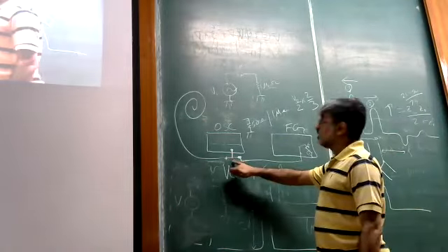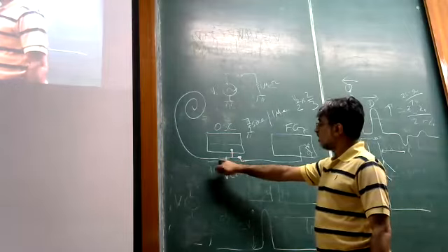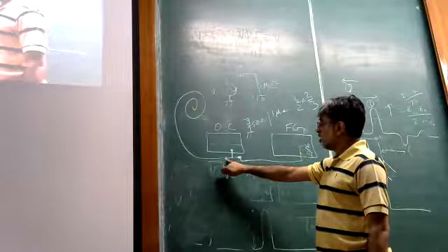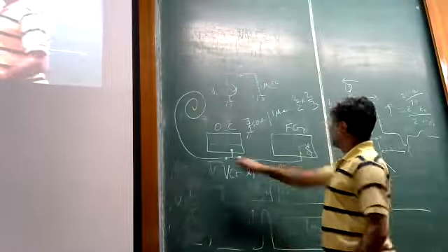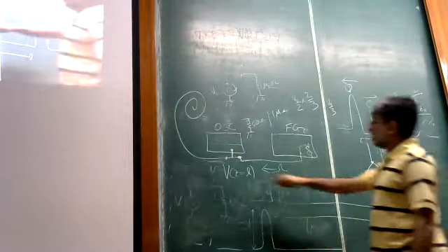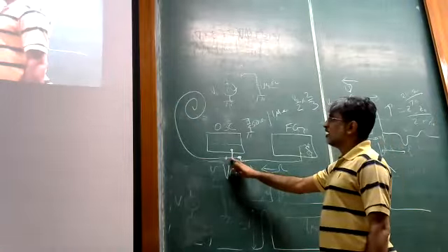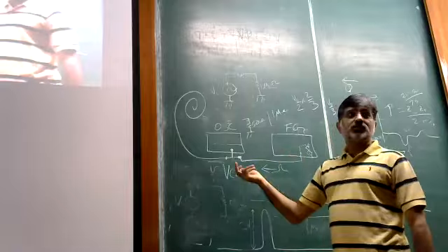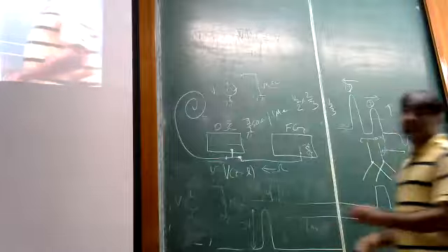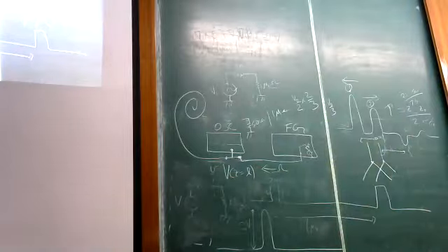So, okay, first transmitted wave continues with the same sign, comes back with a negative sign. So the first pulse you see coming back has become negative. And that negative pulse, when it reflects here, becomes positive, and then it becomes negative again. So, sorry, this is correct. Gap between second pulse and third pulse. Yes. So there is no confusion here, right?